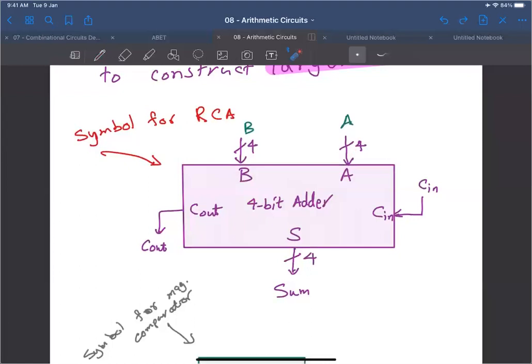Although this input is A, the external input may be different, maybe it's called X. So do not confuse this when you see it later. X is the external signal and A is the internal signal. Just like Verilog: you have a port definition, and when you instantiate, you have a different name for the signal. So the external signal can have a different name from the port signal.